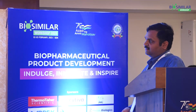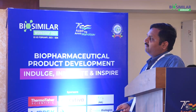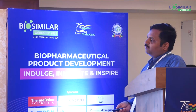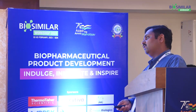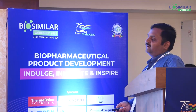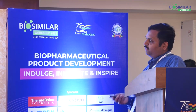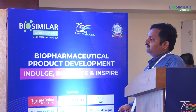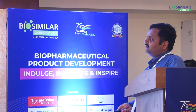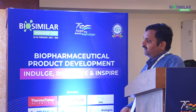Before we start, let's understand what batch to continuous is, and then we can see how it works. In short, in batch mode, we load the complete product on a single column, and it is designed so that breakthrough is not more than 10%. This is done to save the product from going to loss. Because of this, we underutilize the resin, and the productivity is also less.